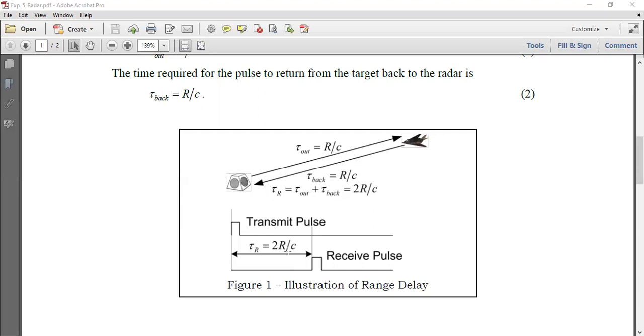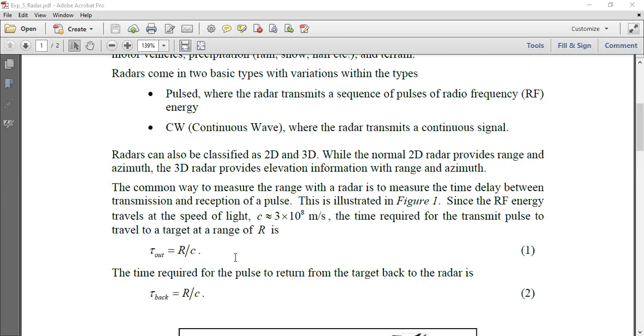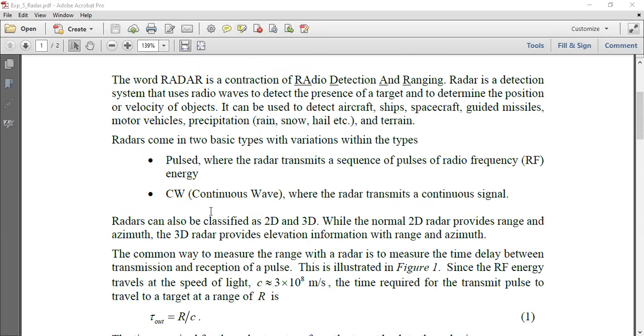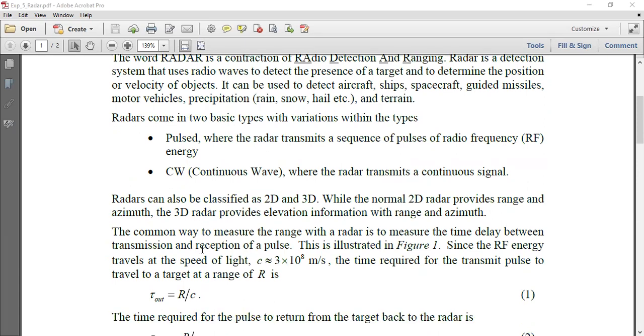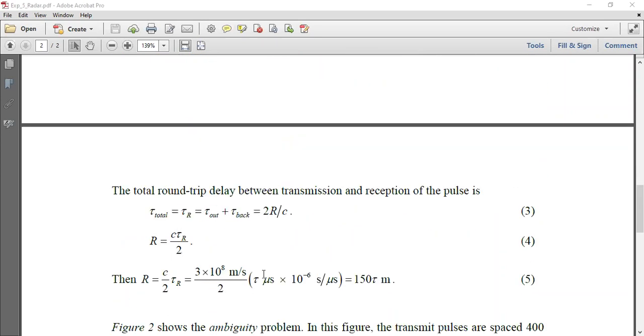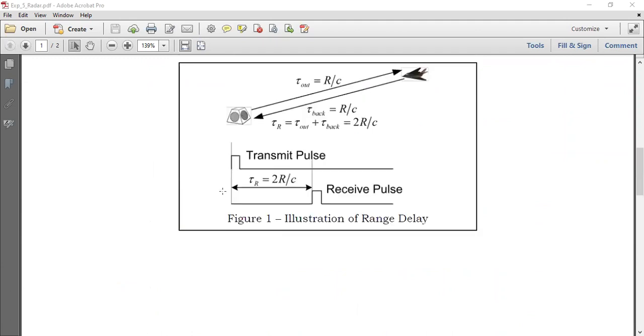continuously. This is why a pulse is usually sent. There is also an option to send a continuous wave, but more commonly the radar uses pulses, and then you call it pulsed. So these are two types, another way to classify the radar. You keep sending pulses one after another. For the first pulse, you expect that the reflected pulse will come back before you transmit the next pulse.